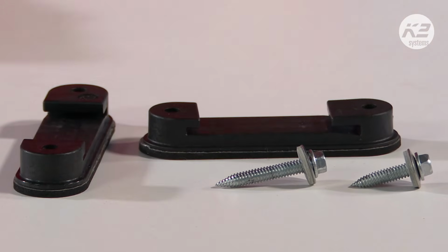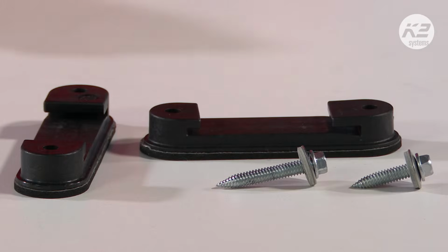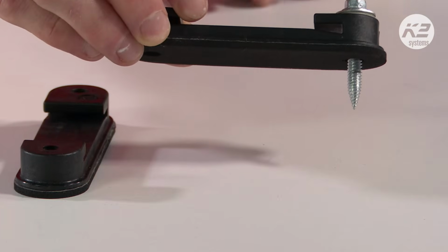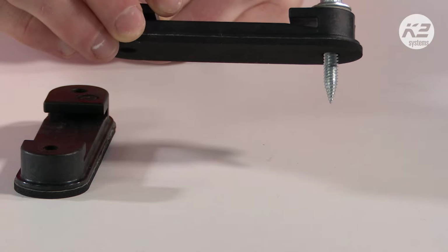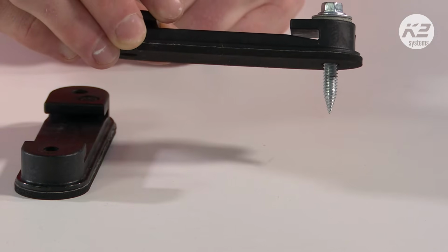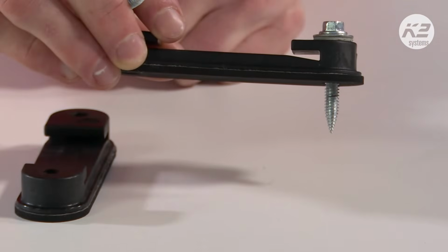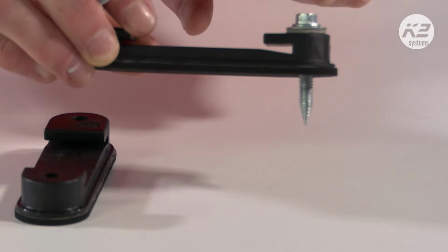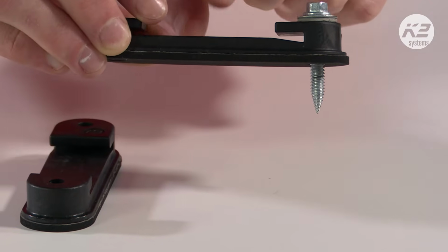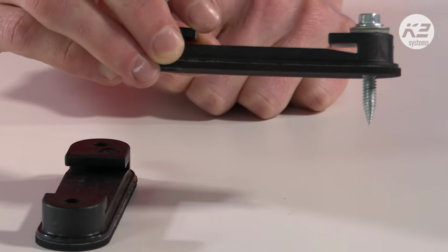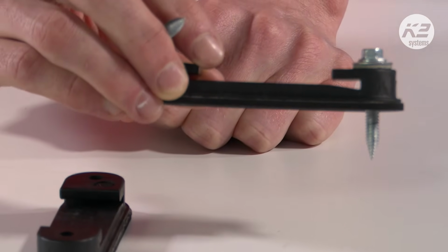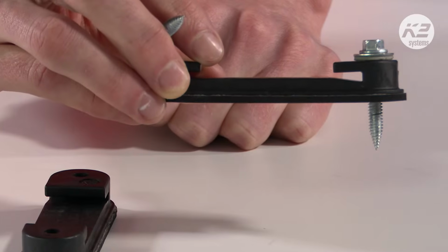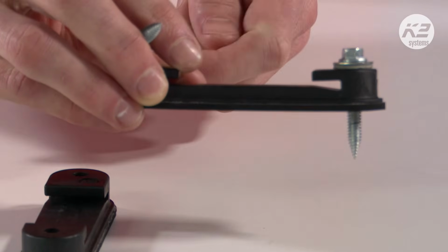Sorry, I just had the product for the mini rail and the multi-rail. The concept's more or less the same. This is going to sit through, and this thread is going to fix into the sheeting. And so our system is only going to be fixed into the roof sheeting, and the basic clips themselves are the things that are being fixed, not the rail. And this allows for a bit of thermal expansion, and we'll talk about that in a little bit more detail.